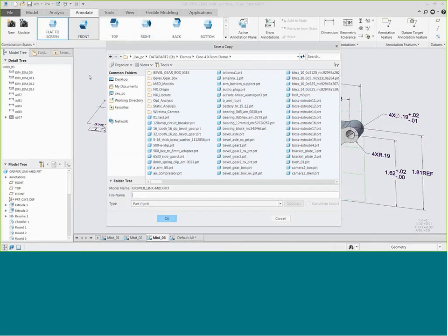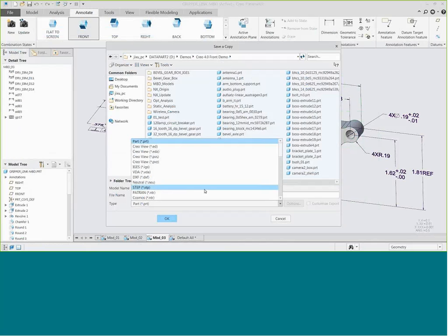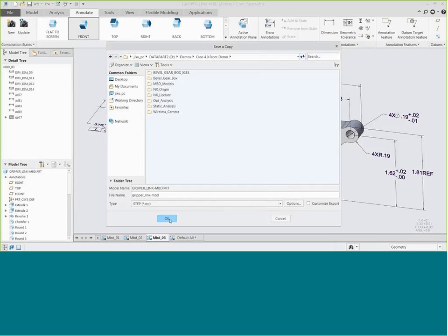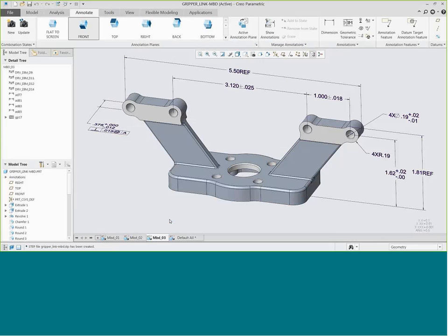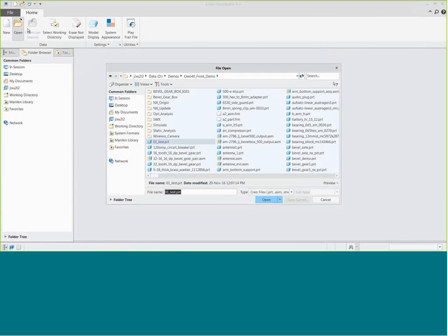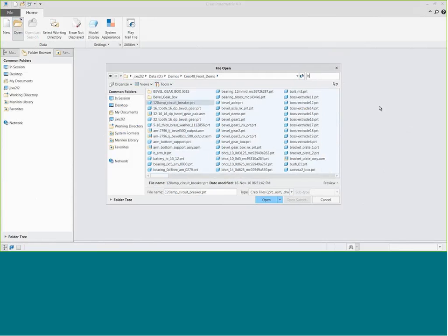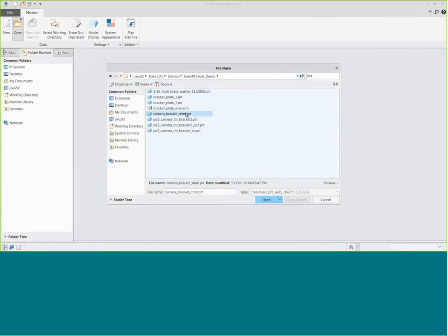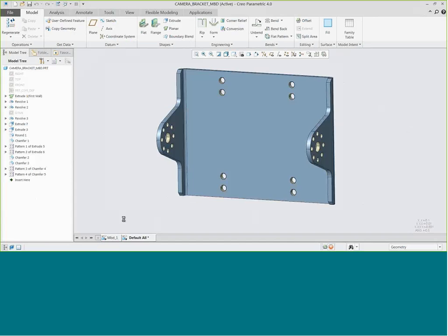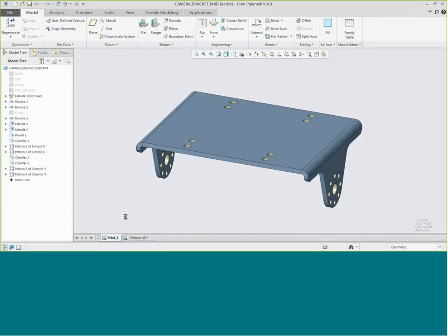So that's looking at the standard functionality available within Creo. What I'm showing here is we can now export this as AP242, and if I pick the annotations and rich content, anybody else that is reading AP242 will be able to get all this GD&T stuff into their system as well. So for example, if somebody is using a manufacturing system, a manufacturing tool, and they read that in using AP242, those tolerances are semantic and they will come across into their system also.